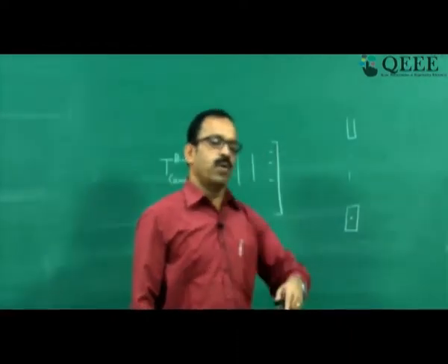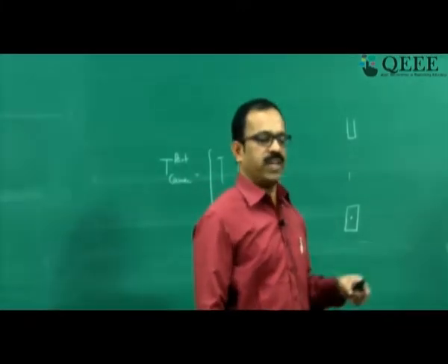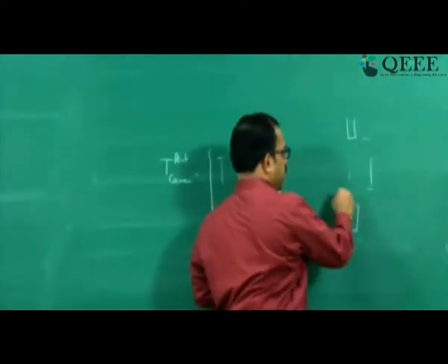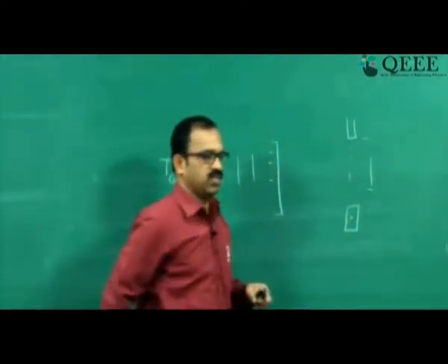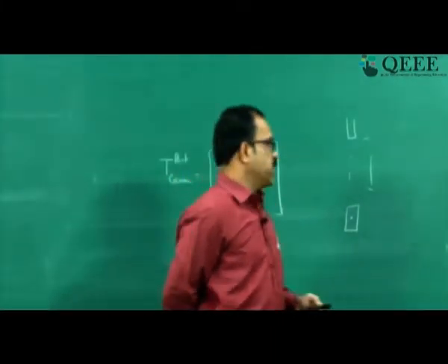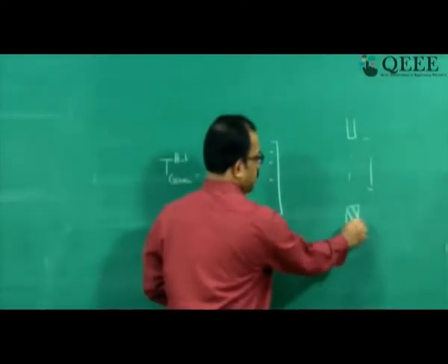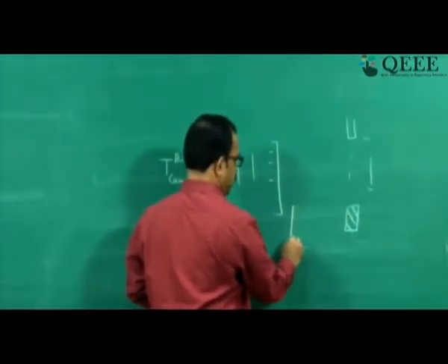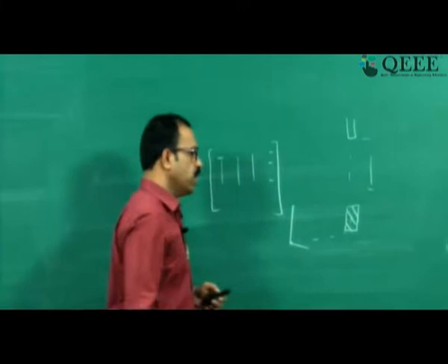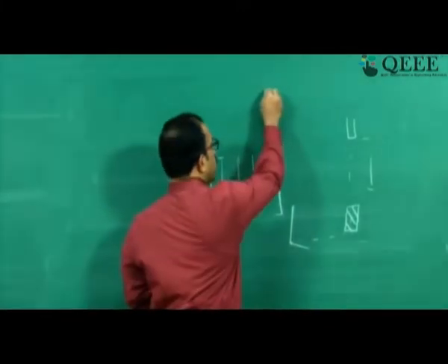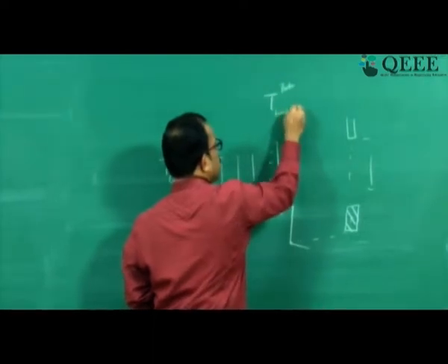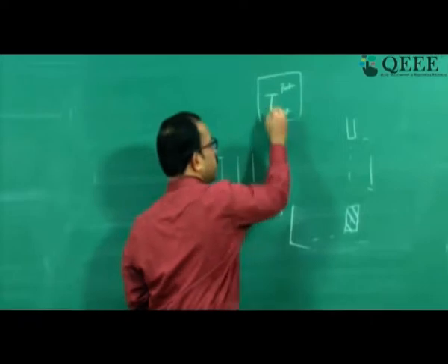So the part is 5 mm away in the y axis and 19 mm below the z axis, given as 0, -5, 19, and its orientation is also given. Now the robot needs to know the position of this workpiece with respect to the robot coordinate frame, because if the robot has to go and pick this up, it should know the position. For that we need to know the transformation part to robot base, T part to base.